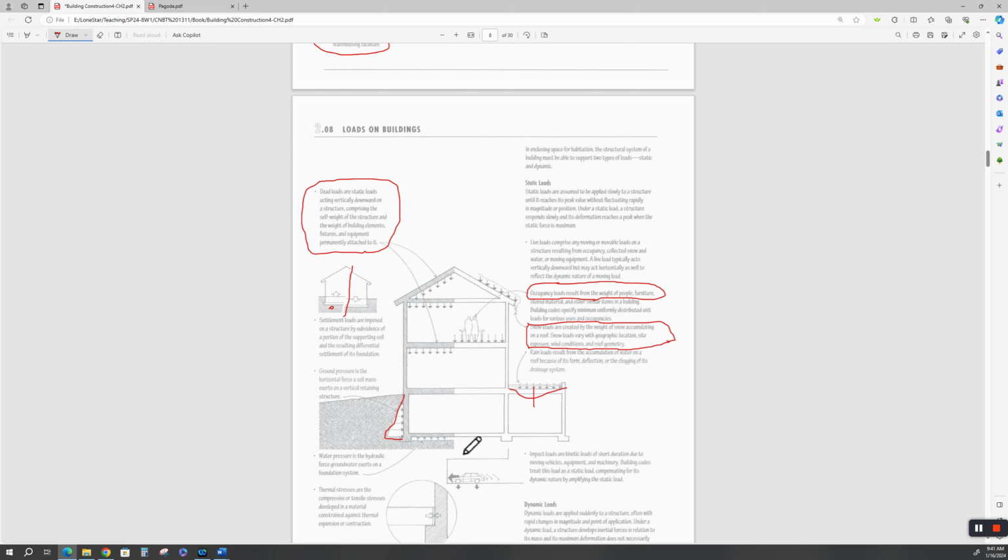This may be a floating slab with crush boxes, cardboard boxes they put underneath here to rot, so as the soil expands or water pressure, it has a gap, a place to go, depending on your foundation engineer and your structural engineer. And again, if you've got water problems, you're going to need a water stop in here, and then you're going to need to coat this wall with an elastomeric membrane to keep the water from wetting this wall and leaching through.